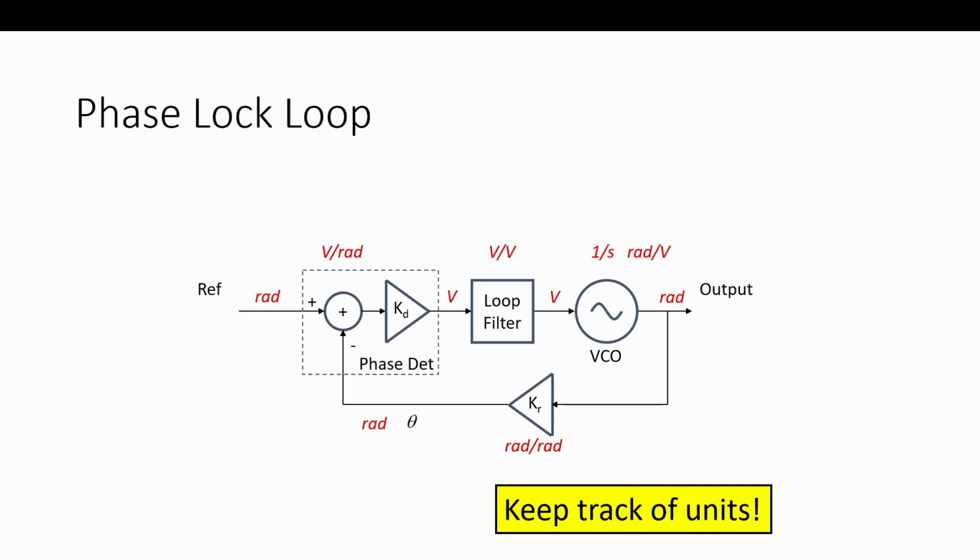And then we have a divider, or would represent a gain, and is converting radians to radians. So it has phase in and phase out. And if it was a frequency divider, it also divides phase. Divide the frequency in half, you cut the phase in half. Go back to the spinning phasor and see exactly how that works.